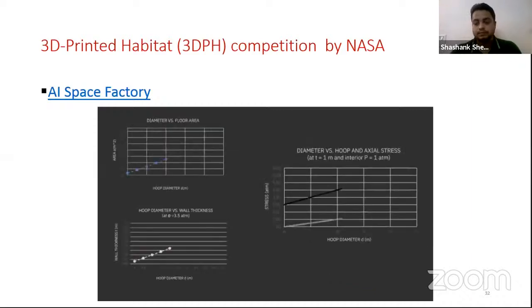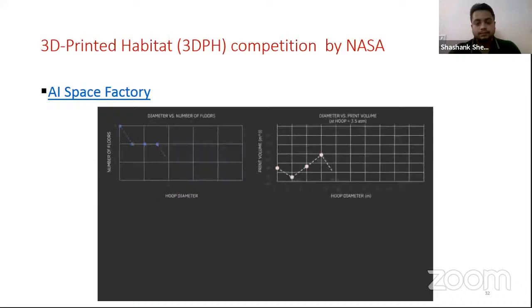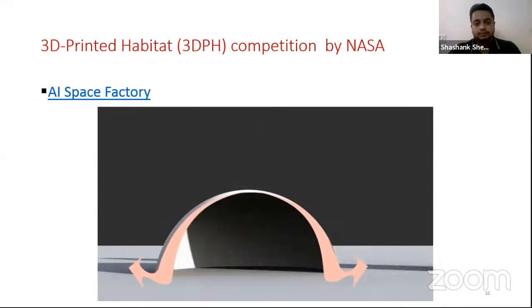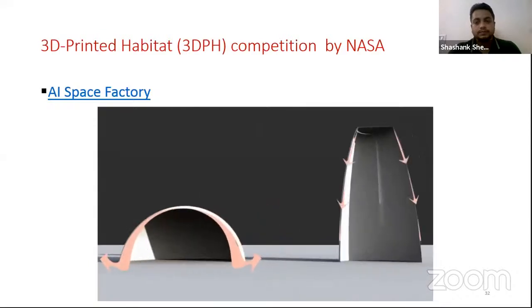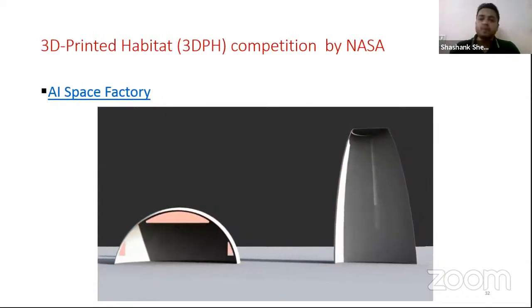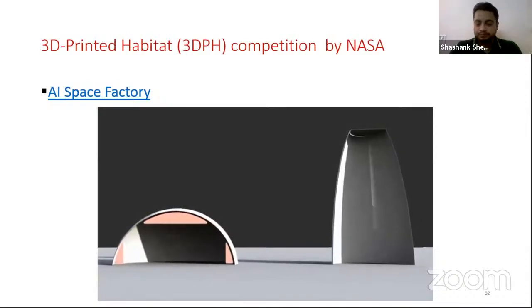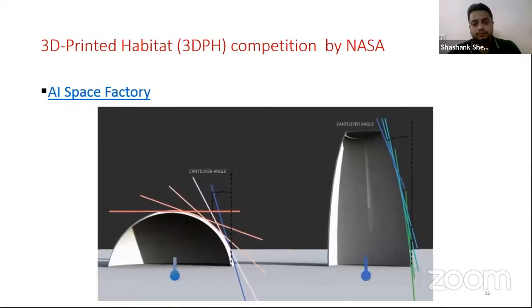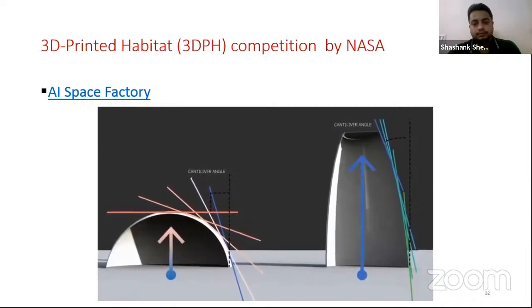Reducing surface area means using less material under less stress. Reducing volume means reducing energy loads on mechanical systems. And reducing diameter directly reduces structural stresses, especially at the base where uplift forces will require anchorage into uncertain ground. Unlike domes, they do not produce unusable overhead volume or unusable perimeter floor area. Therefore, the most direct way to reduce structural loading and maximize usable space is to reduce the diameter and add